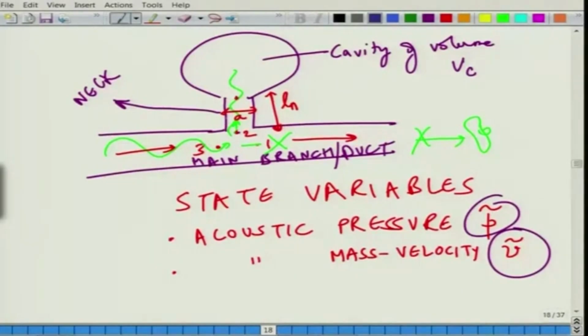So it is like the duct, it is acting like a cavity or certain acoustic pipe which is open at a certain end, actually at both ends, but at each end you can consider this like surrounded with a large infinite flange. Nothing is infinite, but in terms of wavelength, this is much larger than the dimension of the pipe. So you can consider this thing as a flanged end here, and here also the cavity itself is acting like a flange to the duct.